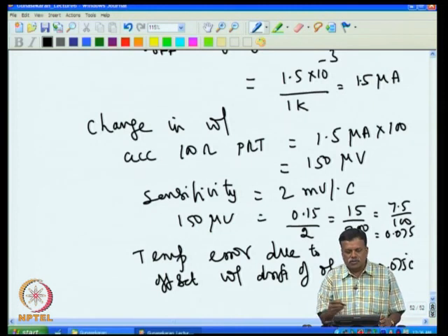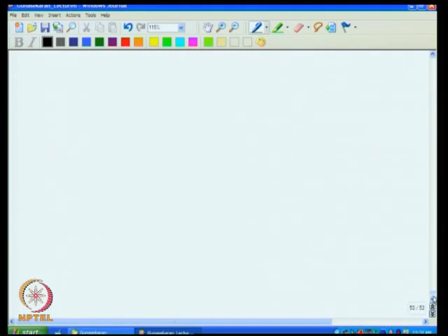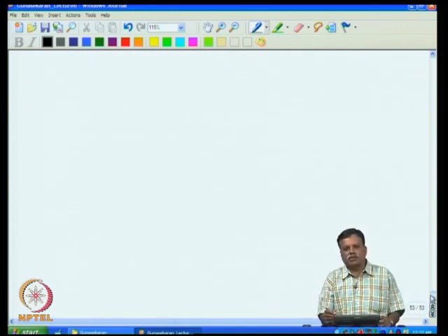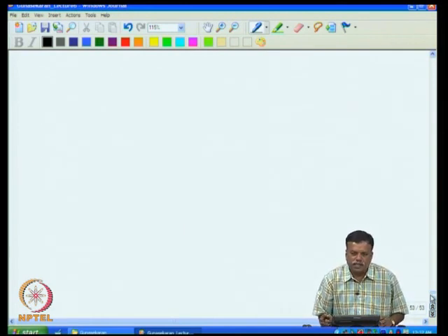So this I have shown you, how to make this temperature sensor for the controller using a platinum resistance thermometer. Of course, we have to now see other issues, because there are so many sensors available, LVDT and so on, which we will discuss one by one a little later, because my aim here is how to design a temperature controller including sensor design and then the heater drive design.